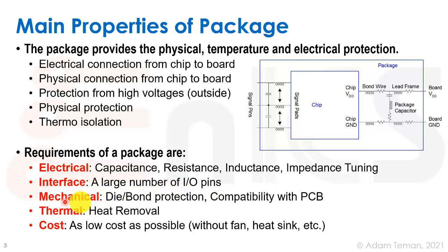It should provide mechanical protection, so it should protect the die and the bond. It should be compatible with the PCB and be able to connect well to it. It should provide thermal protection, so it should allow heat removal. And of course, it should cost as low as possible, so we don't have to add a fan or a